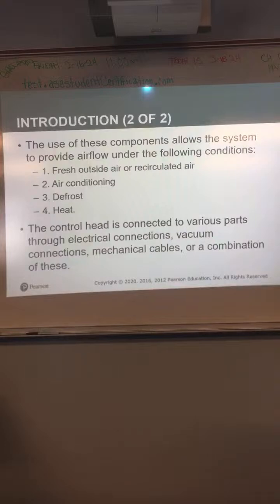If you shut it off, which you can manually with the little snowflake button, then you may have a problem with the window fogging up. But the other instance would be, let's say you had a heater core that was leaking, then it would definitely fog up the windshield really bad, to the point where you probably couldn't even drive the car.